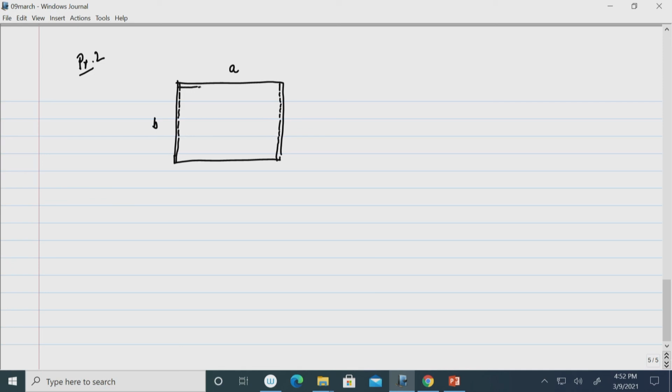In addition, at the other two edges, at y equal to 0 the edge is again simply supported, and here we have taken a fixed edge. So, now you can see this is simply supported, this is simply supported, this is simply supported and this is clamped. Because of the purely unsymmetrical nature, we cannot take any advantage of symmetry, that means omitting two constants and retaining two constants, that business cannot be done here.